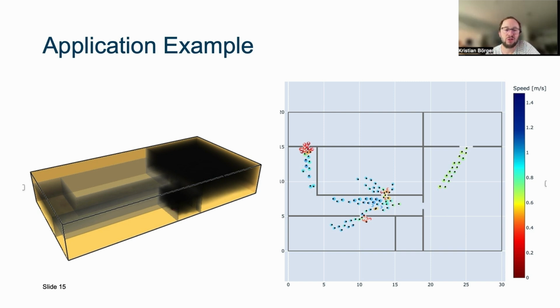You see that at first all of the agents are going for evacuation route 1, and then later on, when the smoke concentration exceeds a certain level, the agents step into the foyer, do not see the exit sign anymore, and then switch routes to evacuation route 2.